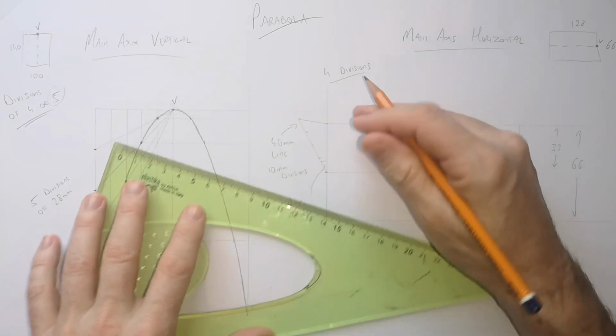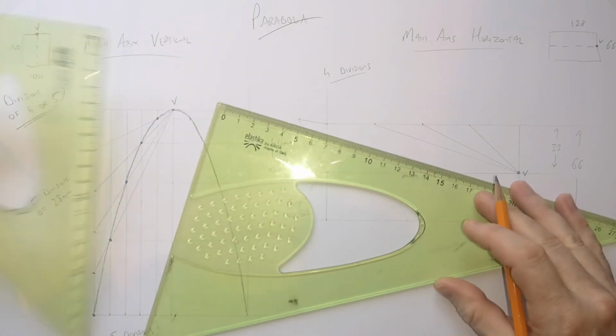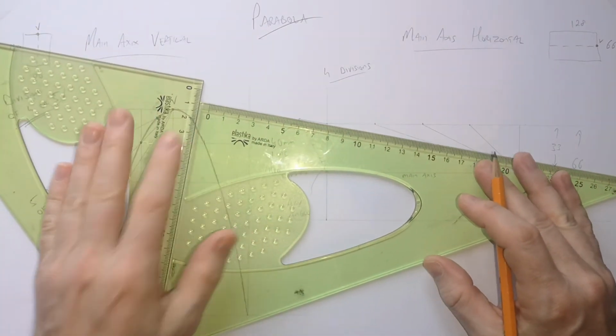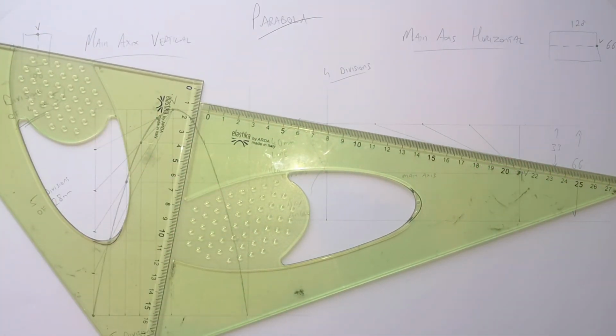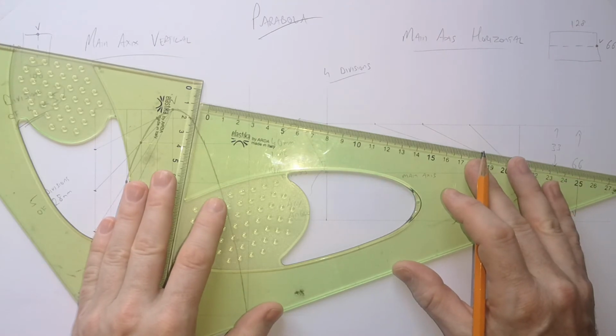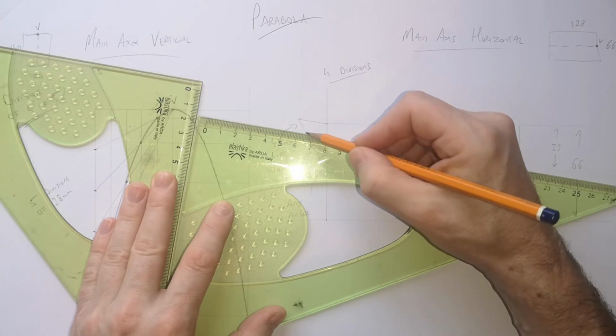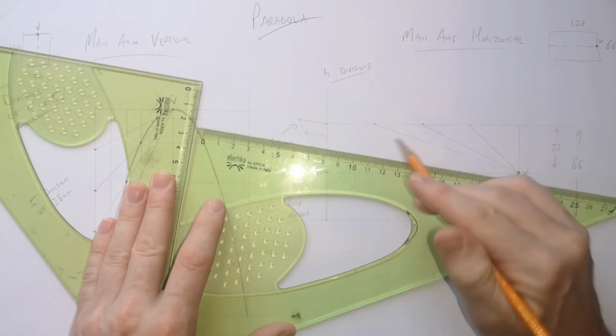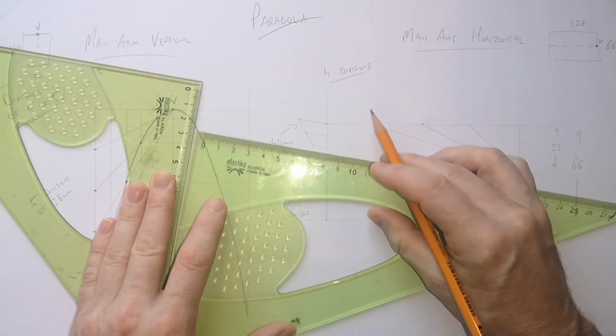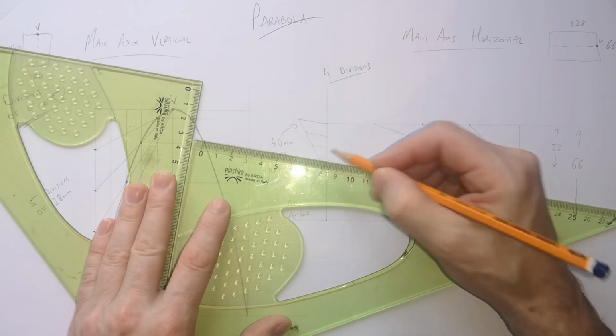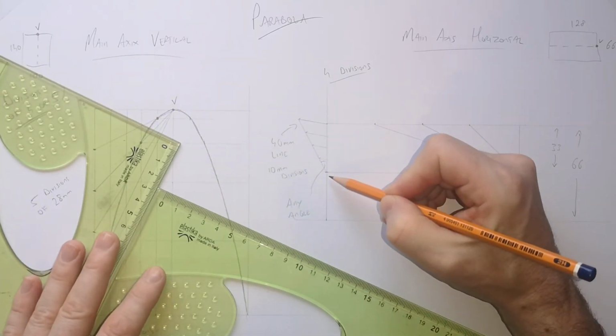Now, we're going to connect the end of that line to the end of the line we want to divide. And all of the other little divisions here are going to be parallel. So I'm going to set up my set squares like this, and I'm just going to use sliding set squares to get my parallel lines. There we go. And now I have 4 even divisions.